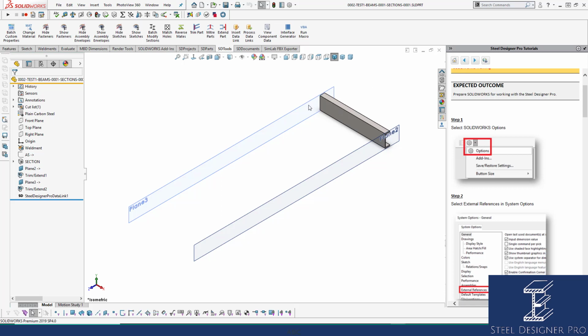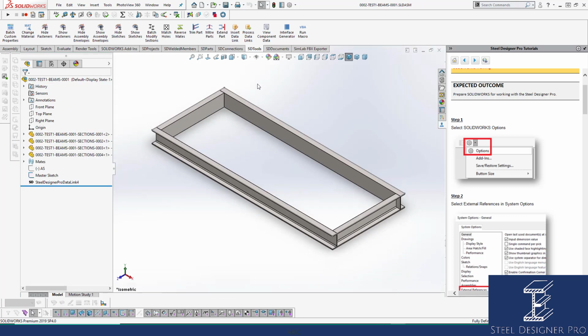By putting a plane in, the rebuild process of the trim occurs against the plane that resides in the same component, and it's much more stable. It does not fall over. And the automatic process of trimming does that for us, so we don't need to worry about that process and the time it takes to do that process.